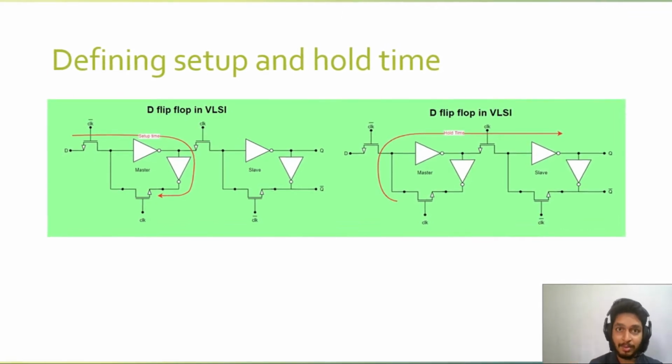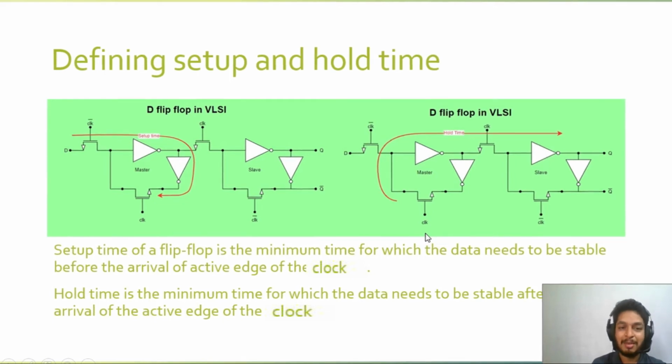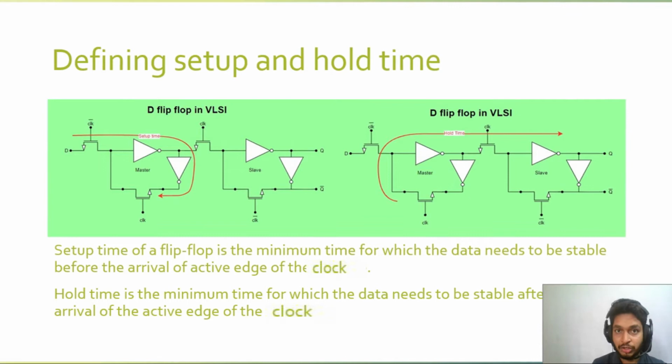This is a requirement, which is the setup and hold time. The setup and hold checks are the checks to ensure that these are done. So let's define what is setup and hold time first, formally. The setup time of a flip-flop, it's related to the flip-flop. It's not related to the timing of the entire digital circuit, which may happen in different scenarios, right?